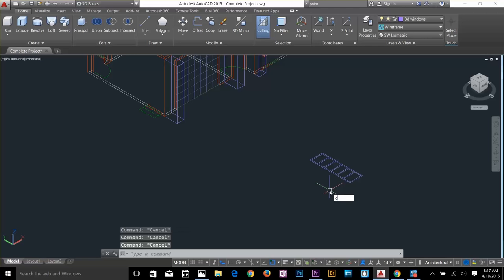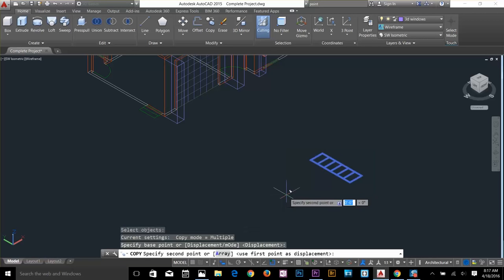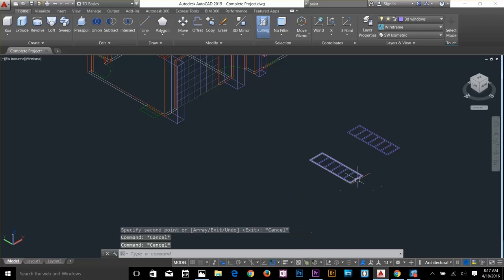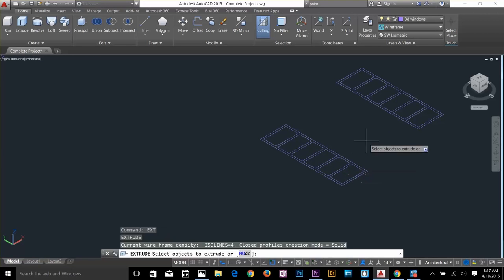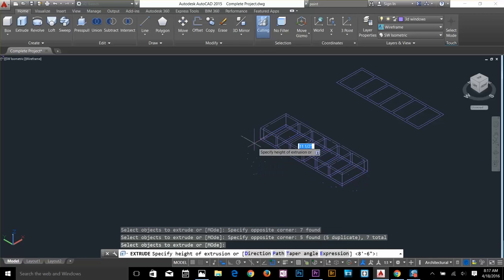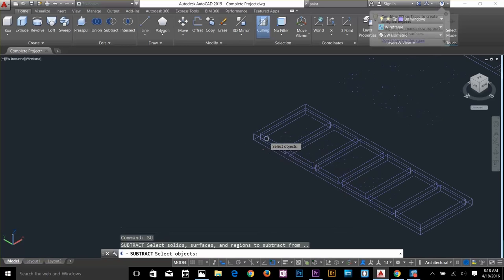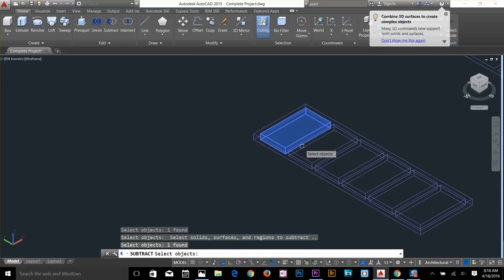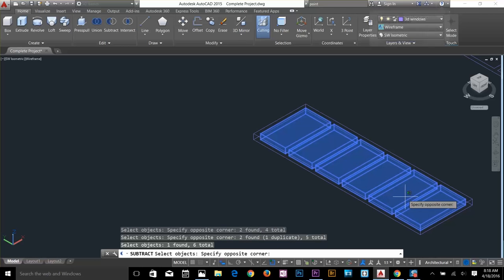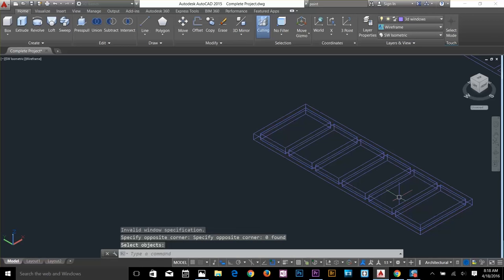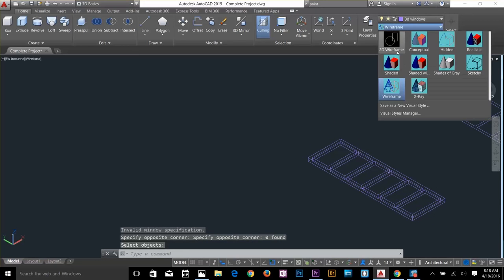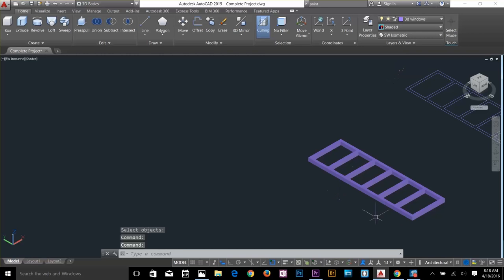and I'm going to make another copy of this about here, and then I'm going to extrude this complete object of 2, maybe 3 inches, fine, 3 inch. And I'm going to use my Boolean operation called subtract and get rid of all these inside parts. Alright, so now change your viewport to shaded. Now you can see you got this.